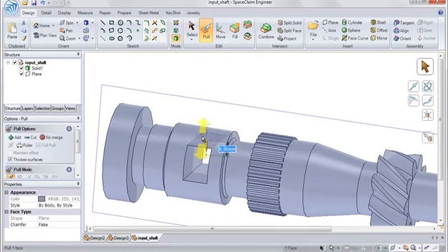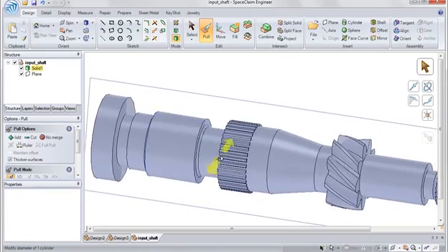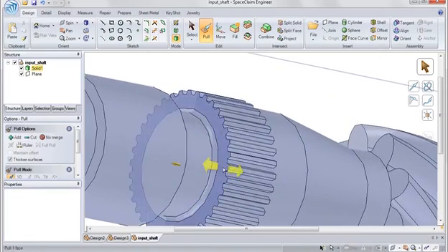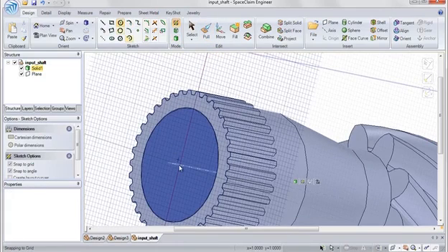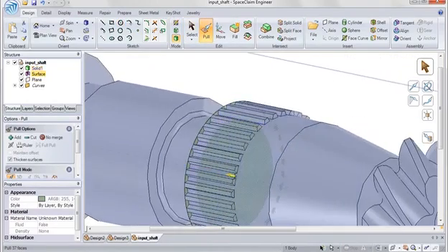This cutout here, that'll be added in a later step, so we can just go ahead and pull on those faces to remove that. And the knurl on this section, might want to get rid of that. That's obviously going to be a separate step. So we'll just create a quick circle and pull that across using the pull up to reference the opposite side.